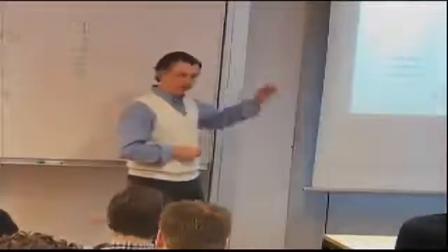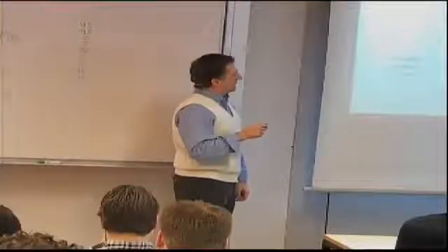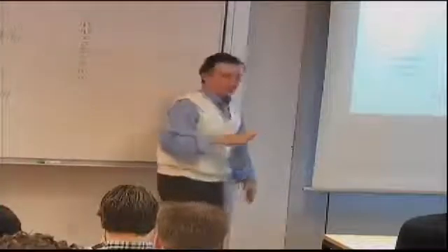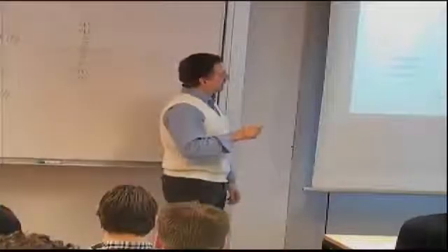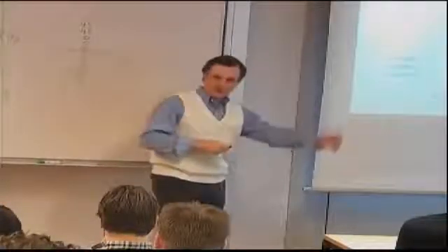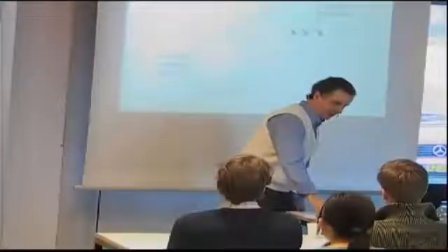Now there's one slight thing here that I am omitting for now. Because the stiffener actually is loaded, let's say, along its neutral axis, then it's not simply an in-plane load here at the skin, but there's also a bending moment because of the load being eccentric. We are neglecting that, and we've done the solution. A master student has done that, so it's not that it cannot be done, but it takes a lot of algebra. Why are we doing this now?